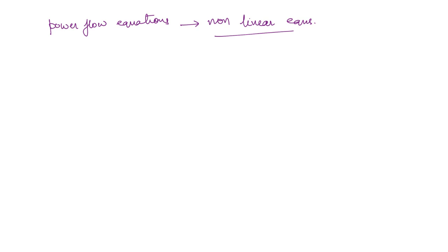So load flow analysis requires us to solve the power flow equations that we saw in the previous lecture. Now the power flow equations are non-linear algebraic equations. If a linear equation is given, then it is easier to solve, but when a non-linear equation is there, then how do you solve? For this you are going to use the iterative methods